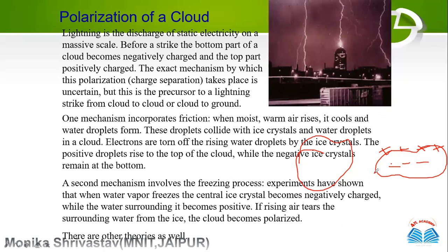Now there will be a phenomenon of polarization, as you can see here. The positive charge cloud will be on one side and the negative charge cloud on the other side. When the cloud gets dense and it starts raining and two clouds strike, polarization happens in the cloud, and that is why an electric field is generated inside the cloud. You know that is your secondary electric field.